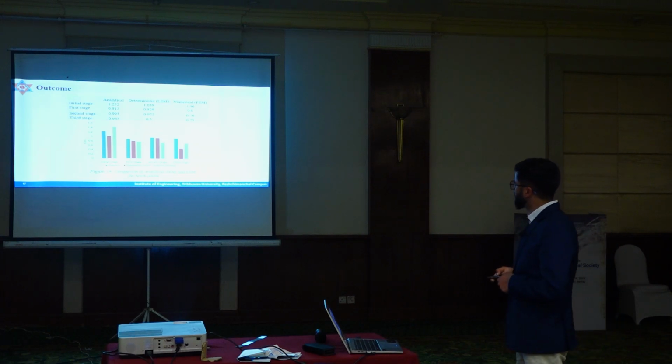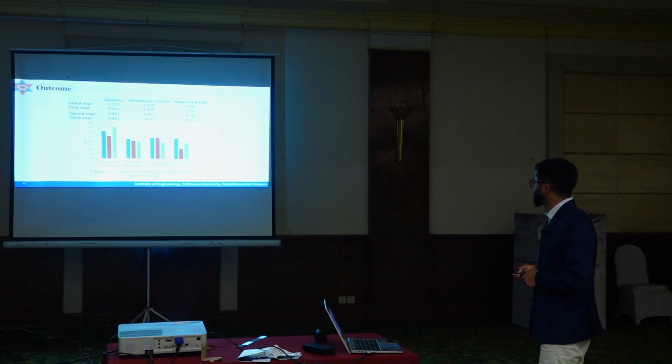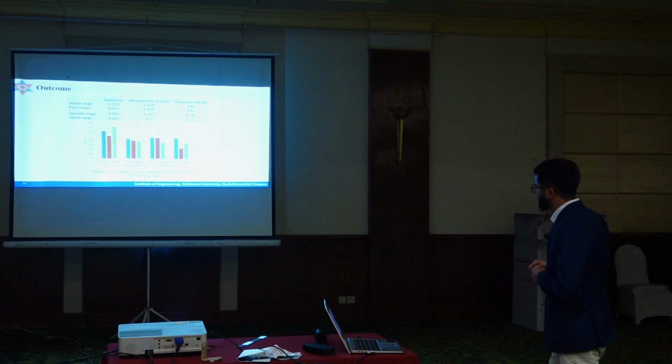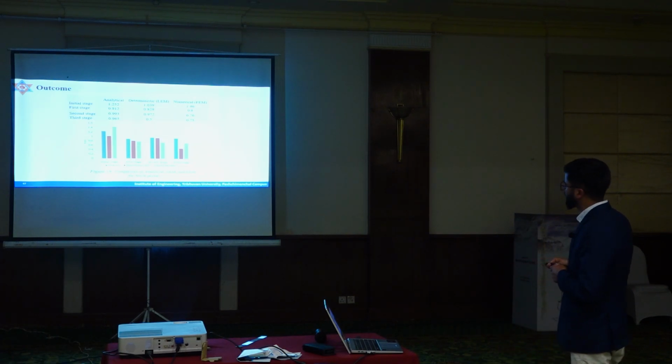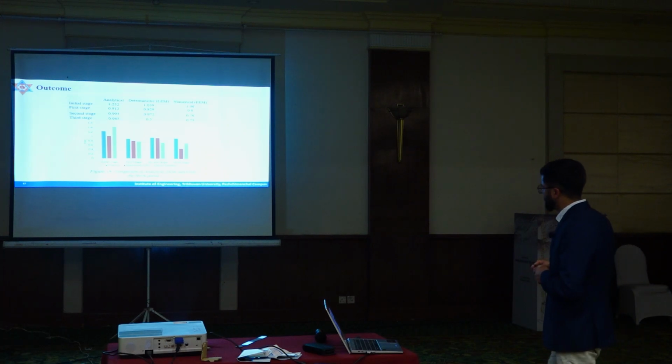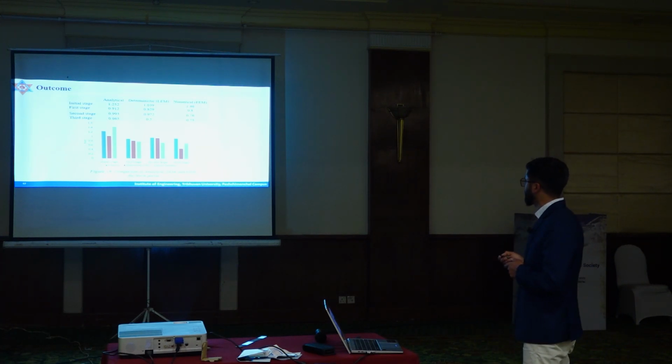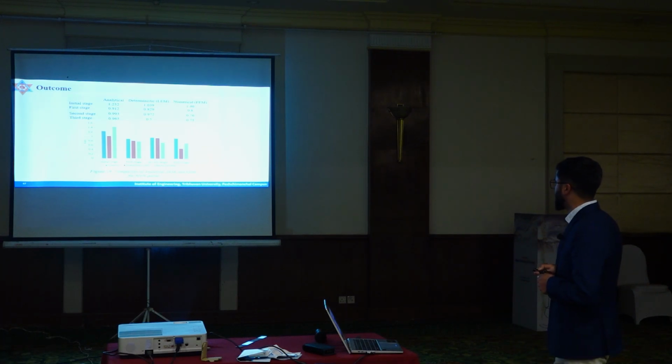This is the outcome from all the analytical, deterministic and numerical analyses. Here at the initial condition, the portal is safe, that we can see, and here at the first stage of excavation, the portal is unsafe, with a factor of safety less than 1. At the second stage of excavation, the factor of safety slightly increases due to the bending effect, and at the third stage of excavation, the factor of safety further decreases and is less than 1. It shows